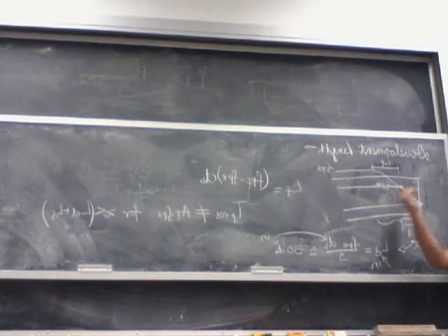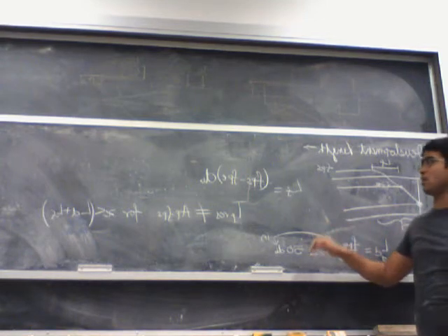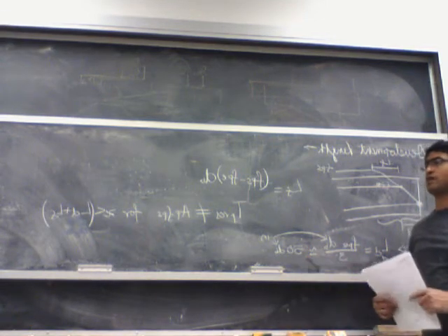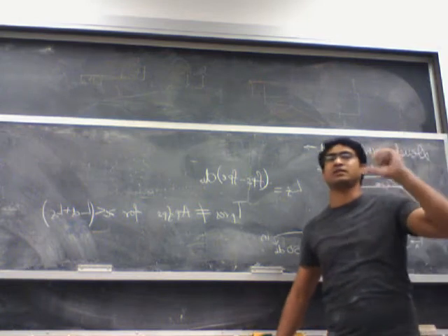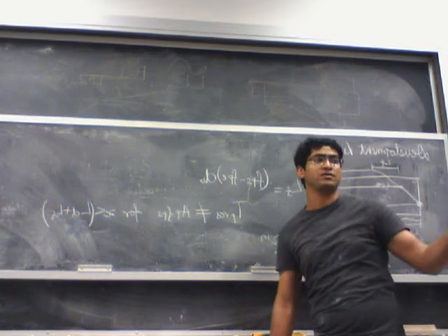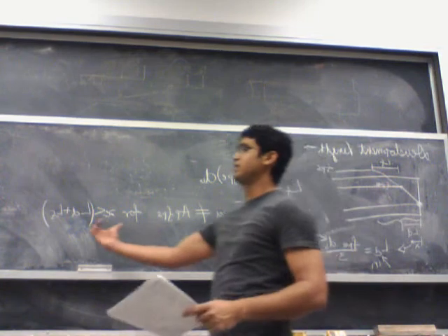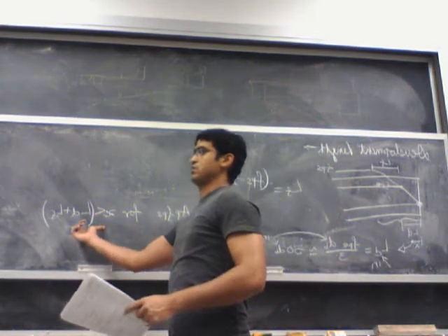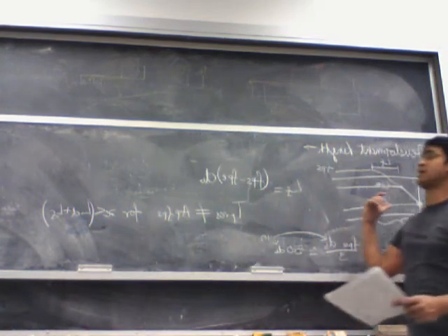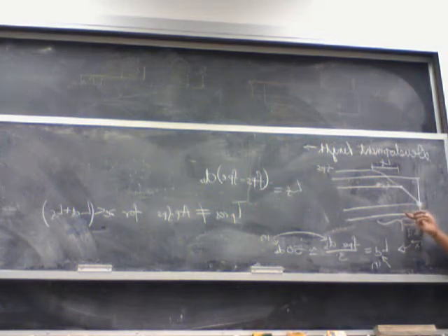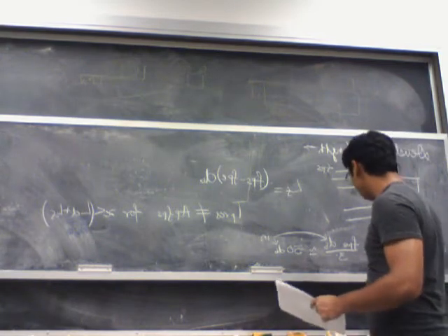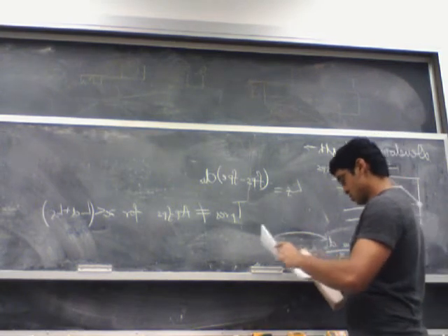So now if you go back to how we calculated the moment capacity of the cross section, we assume that my tension in the pre-stressing strand is actually AP FPS, which is not the case within this range. So that will directly affect the nominal moment capacity of the beam itself. And then this also has an effect on the shear capacity of the beam, which I'll go into next.